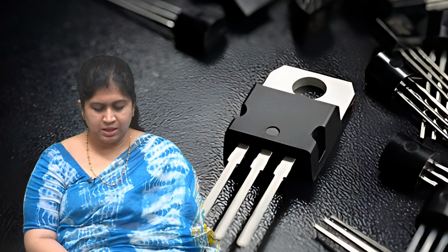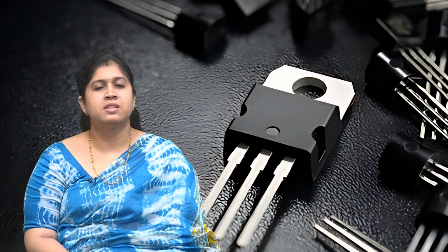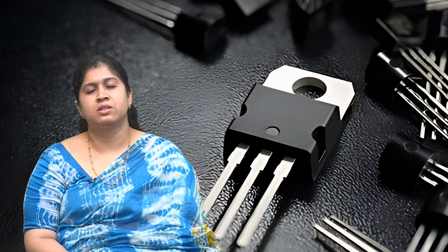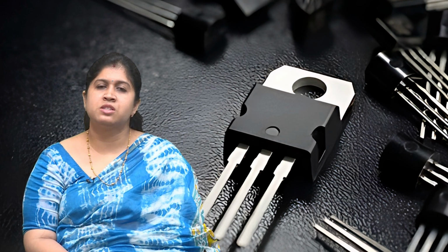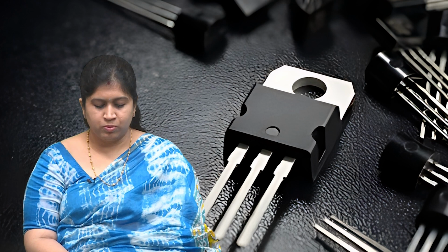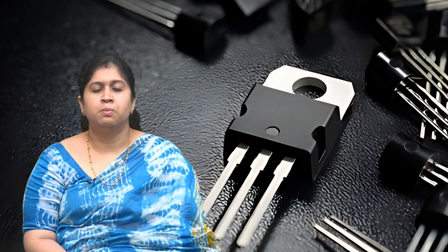To conclude this session, in this section we discussed in detail the bipolar junction transistor, the working of the bipolar junction transistor for NPN as well as PNP transistor, and for both transistors we discussed the three modes of operation: cut-off region, active region, saturation region and also the reverse active region. The most important that we discussed in this section are the cut-off region, active region and saturation region in detail. Now in this section we completed the bipolar junction transistor operation. Thank you.